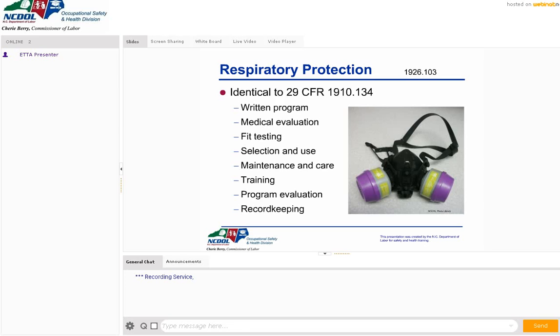In some cases, we are going to look at these old buildings and just make the assumption that they have asbestos insulation, because a lot of them do, okay? Especially if they're commercial buildings, old buildings downtown, old brick buildings, old factories, things like that. Really not a whole lot of asbestos was used in, say, residential building, except for things like some linoleum floor tiles and things like that. So it's important to remember if you're doing old construction or renovation of an old building, you may run into asbestos.